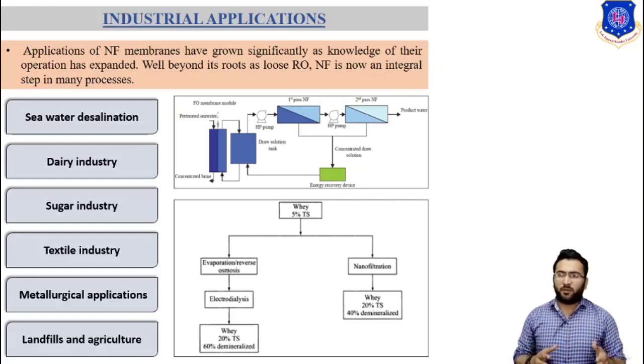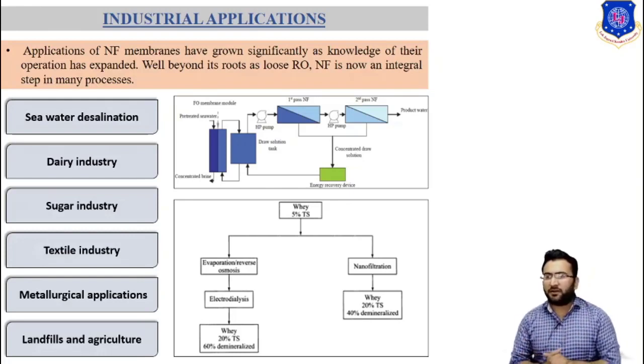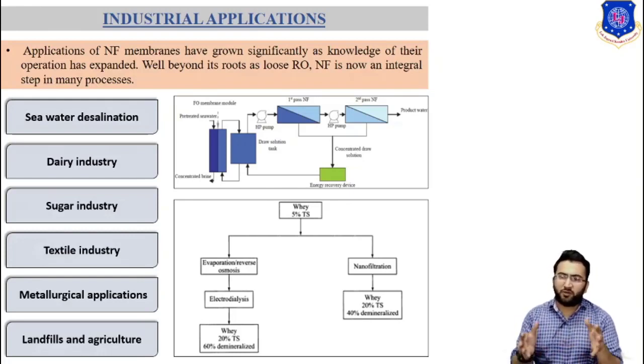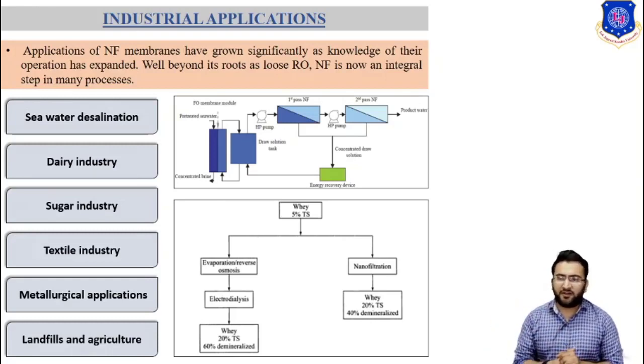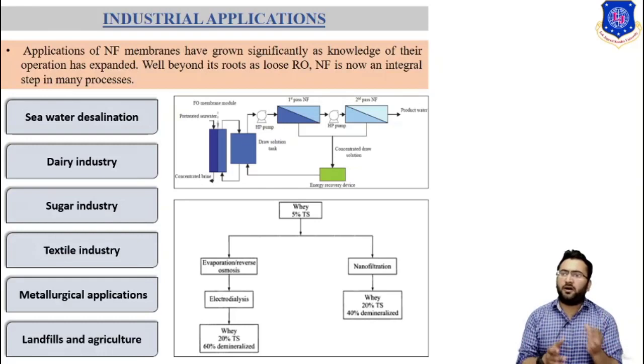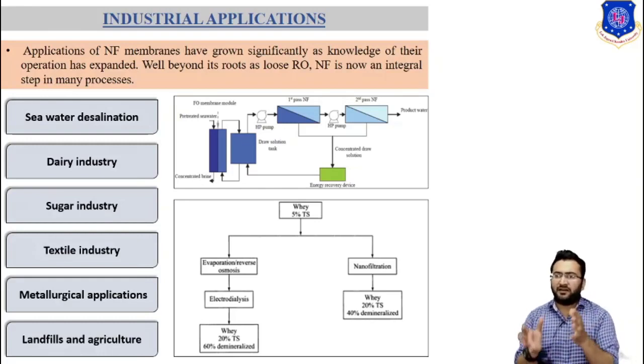One of the major problems in efficiently desalting seawater is the tendency for the reverse osmosis membrane to become fouled with salt and organic material. UF can remove this constraint before the water reaches the RO membrane, reducing fouling and increasing efficiency. Nanofiltration is used to soften water and clean up streams, completely removing mono ions and other unacceptable or undesirable ions.